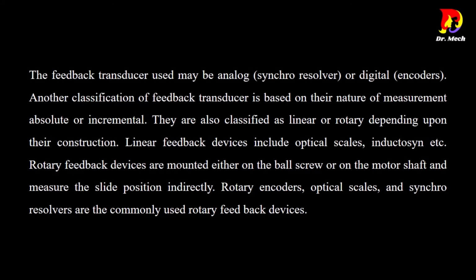The feedback transducer used may be analog, synchro resolver, or digital encoders. Another classification of feedback transducers is based on their nature of measurement: absolute or incremental. They are also classified as linear or rotary, depending upon their construction.